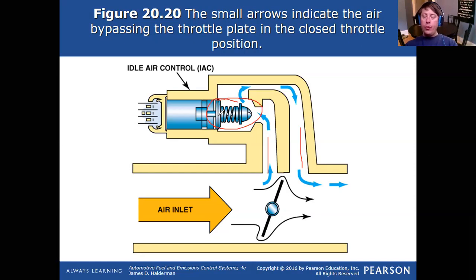One of the ways you can try to diagnose these is with bidirectional controls. So in your scan tool, you can go into bidirectional controls and you can take control of your idle speed control motor. So you can actually try to run the RPM up and run the RPM down. And one of the things you can do while in bidirectional controls is cycle that idle air control motor 3 or 4 times in an attempt to break up maybe carbon that is stuck inside of it. So anyway, idle speed control motors have disappeared. They're gone in modern cars.